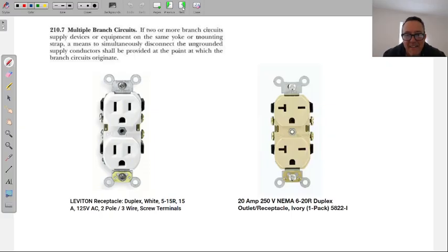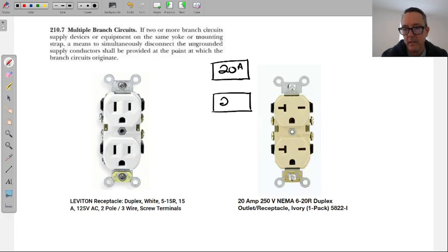Oh yeah. So here's my situation. And by the way, I had a friend that called me with a problem, so I'm gonna place a troubleshooting problem in front of you. So here's what they had. They had one breaker, 20 amps, because it's a kitchen, and we'll look at that. This is in Article 210, gives us this as well, tells us what these outlets have to be, or circuits have to be rated at. So I have two individual 20 amp circuits. I have A phase here, we'll just say that's the A phase one. We have B phase, we'll represent it in B phase color correctly.